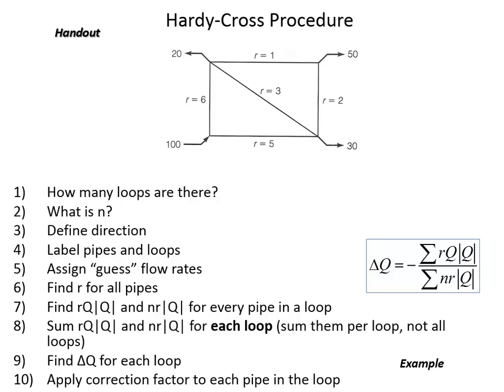And how that comes into play is we're assuming that the water goes this way and this way to begin with, right? So this flow is going to be a positive flow. When we go through our numerical procedure, the vertical pipe, since it's in the same direction as that loop, you can see that the loop would say positive is up for that pipe. But for the horizontal pipe, that flow to the right is against the positive direction that's defined by this little clockwise is positive notation.